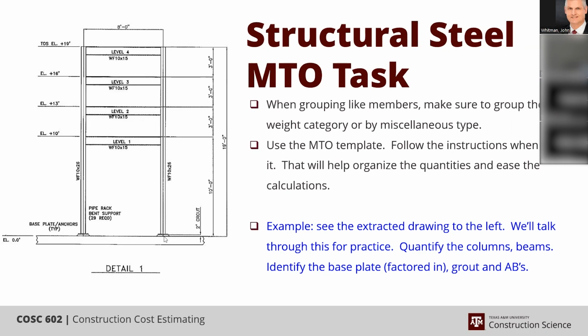So by the time you're done with all your steel structures, you have all of your grout underneath them. Then all you're left to figure out is your unique grout pours that are standalone for whatever reason, and the grout that belongs to your equipment, and you can take that off when you're calculating or installing your equipment. When you're done, you should have all the grout required at that point in time.